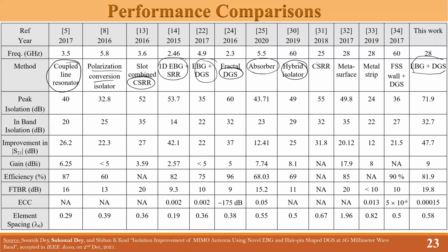CSRR also, and some of the metasurfaces, something close to AMC. Let me tell you that this metasurface has actually come from the artificial magnetic conductor era. If you are talking about any AMC, any artificial magnetic conductor that can be defined, you either have negative epsilon with positive permeability, or positive epsilon with negative permeability. That can give you a single negative structure.